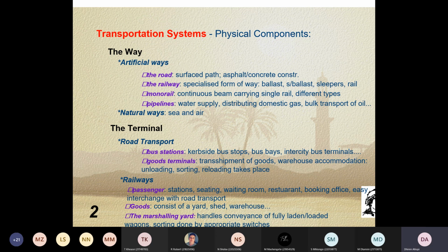Goods, yes, where you have certain sheds, warehouses, yards, goods yards, marshalling yards. So you have, for example, a rail system that gets your trains with your goods onto the warehouse. You may have covered rail design, I think, in 2A. So you would have dealt with terminologies like switches, turnouts, crossings, where you are given priority by a simple switch. Your train will then be directed to maybe the right-hand lane or rail or straight ahead by simple switches.